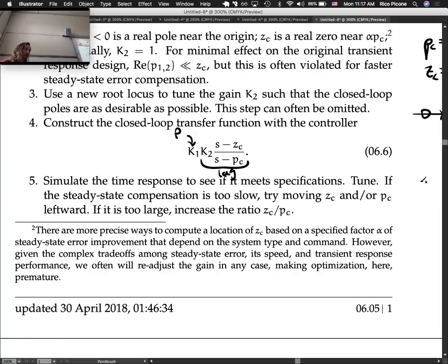So the way that actually works is you have your measurement, which is probably like a voltage, right? So you take your measurement, which comes from an encoder in the case of a motor, typically. So you have the position of the motor, and you subtract, this is typically done in software now, the position that you want from that, and then you multiply it by our gain or whatever, and you say this is how much voltage we want to supply to the motor to make it go to the right position.